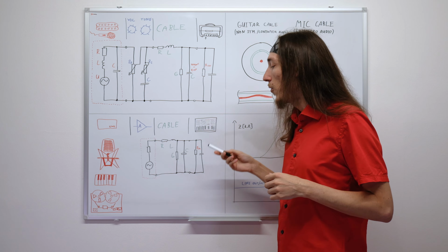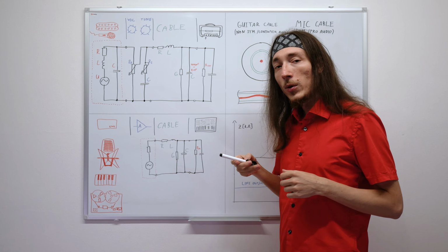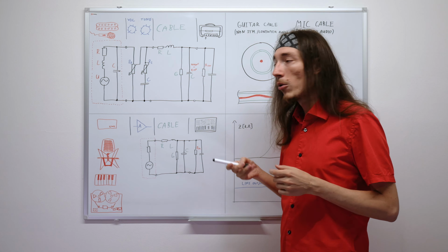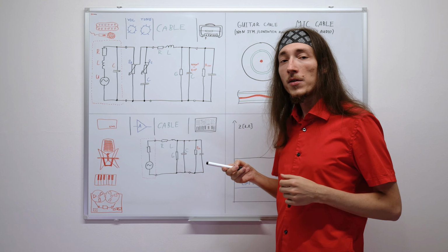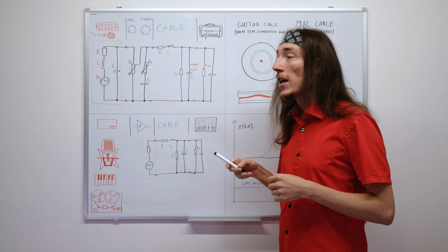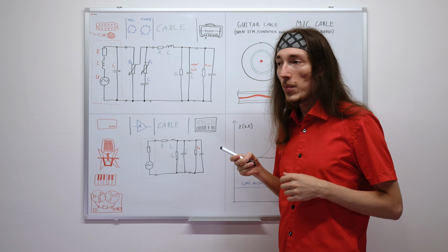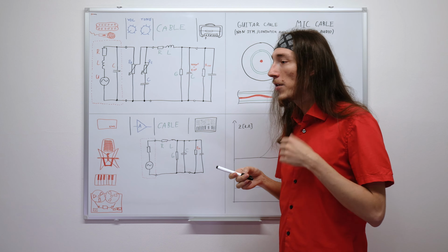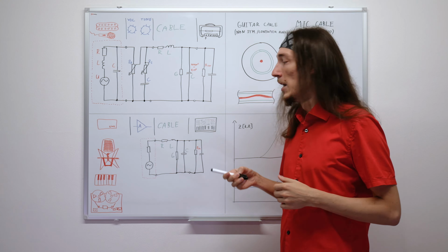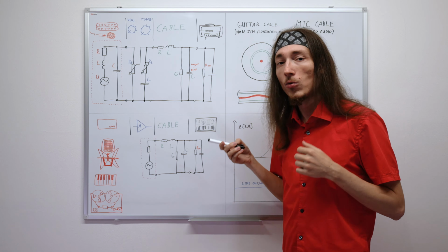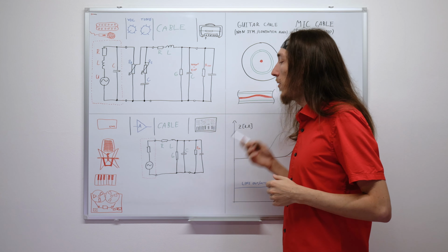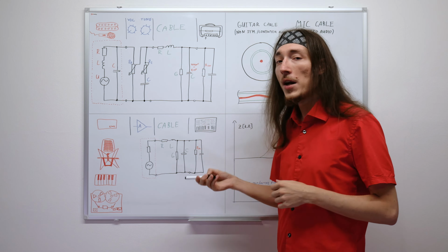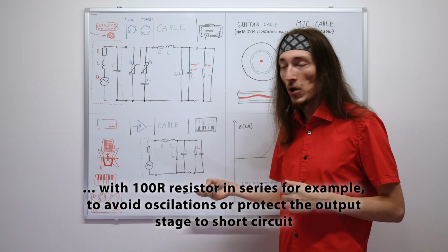If we are designing, for example, line outputs from the sound card or from some mixing console, we want to run more than 10 meters of cable. In some studios or in live situations, there may be 30 or 50 meters of cable. We have to be able to run this cable, so the source impedance should be very, very low, actually a fraction of ohms.